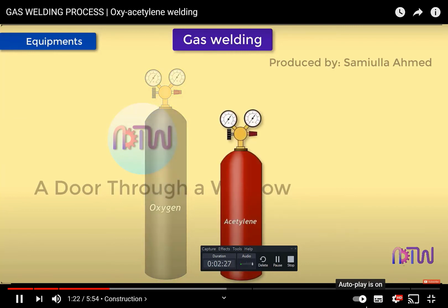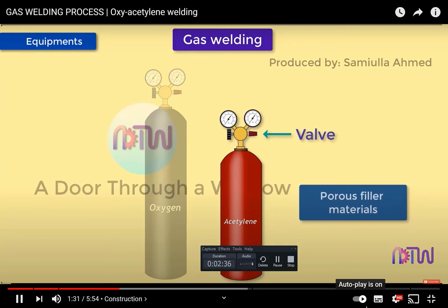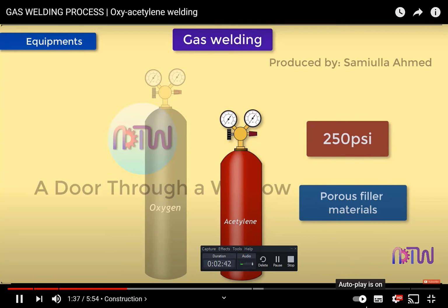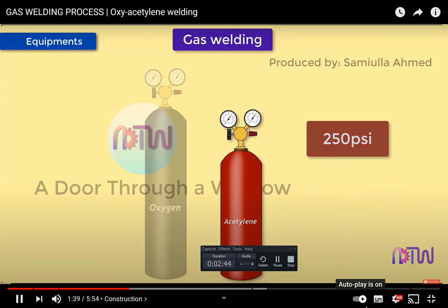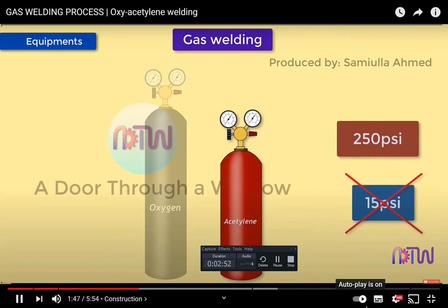Acetylene cylinders. These cylinders contain acetylene under pressure, made of steel and have cylinder valves. The cylinders contain porous filler material, which is fitted with acetone, that allows the acetylene to safely be contained in the cylinder at 250 psi. Acetylene should never be used at a pressure that exceeds 15 psi, as it becomes highly unstable, which depending upon the condition could cause it to decompose and explode.